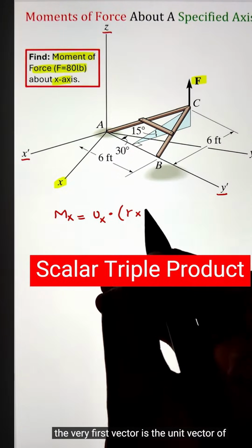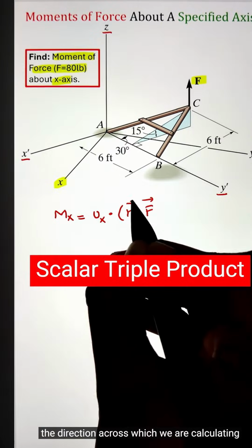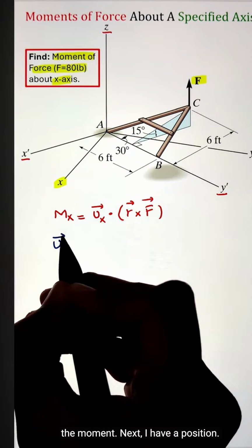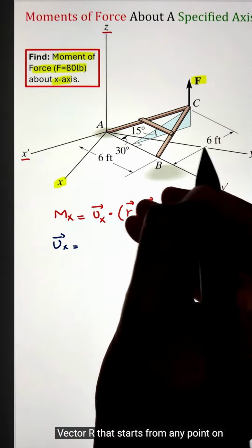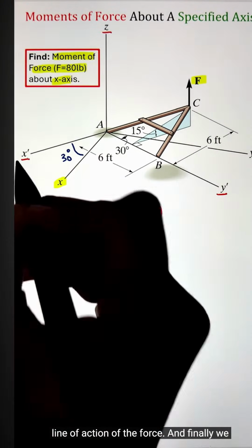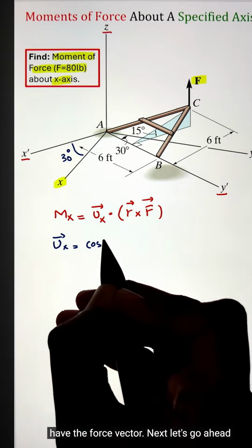Starting with the very first vector, it is the unit vector of the direction across which we are calculating the moment. Next, I have a position vector r that starts from any point on the direction at which we are calculating the moment and heads towards the line of action of the force. And finally, we have the force vector.